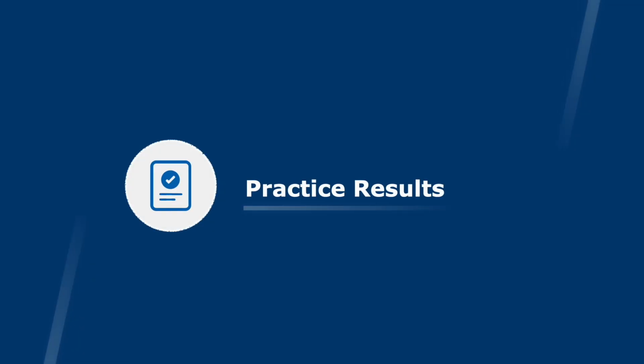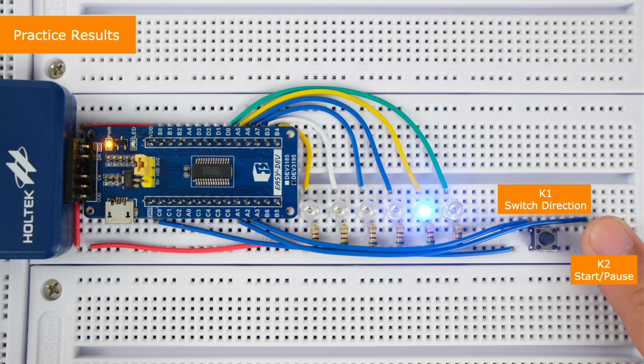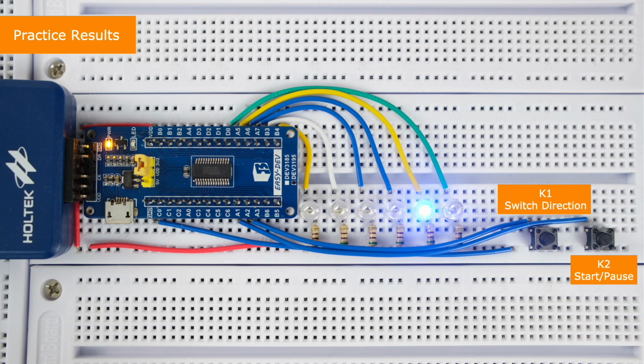Practice results. After the MCU is powered on, all LEDs remain in the off state. When the K2 key is pressed, the running lights start operating, moving in the left direction. When the K1 key is pressed, the moving direction is toggled. Press the K2 key again to pause the running light effect.